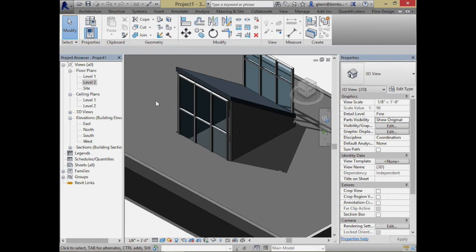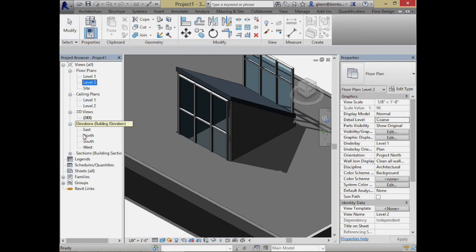Okay. So would you say that it's almost always better to do it the other way, facing north? If you're trying to get daylight, and actually, yes, in a lot of cases, and every building's a little different. It really depends on what you're trying to maximize. But even something as simple as, if I put the little glass pyramid like the Louvre up there, then I'd have daylight, I'd have a lot of sunlight, I could get some solar on one side, but just the shape can totally affect what your potential is for that. Actually, I'll give you one more thing about this funny roof, just to complete the discussion.